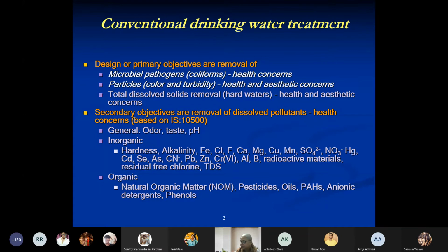I don't know how to describe musty, but most of you have probably seen it either in bottled water or sometimes in lakes. If you go to lakes and they're not very clean water, you will find a certain musty odor. And that odor again is sufficient reason for rejecting it. pH is, like I said, if it's acidic, you will reject it. If it's highly basic, you will reject it. So these are basic ones.